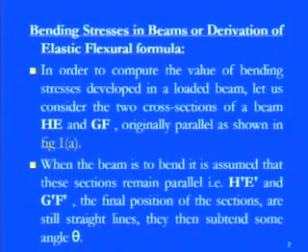So first of all, as we discussed, the bending stresses in the beams, or the derivation of the elastic flexural formulas, because first of all we need to see how the bending stresses will form, and then how they will be distributed all along the entire span of the beam. In order to compare the value of bending stresses developed in a loaded beam, first of all we need to consider two cross sections of the beam, HE and GF, originally parallel, because when there is no bending moment they are absolutely parallel to each other.